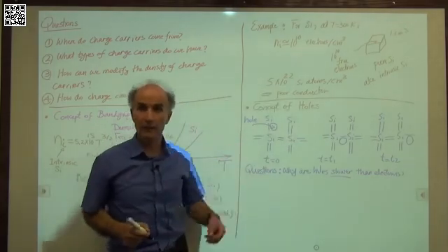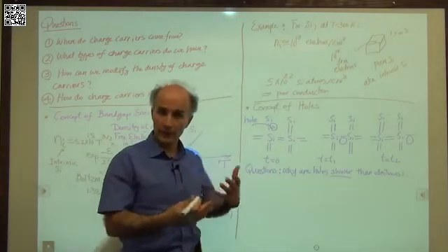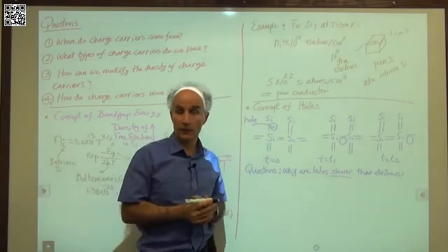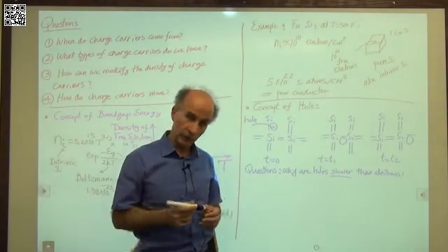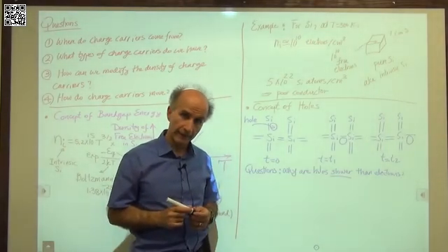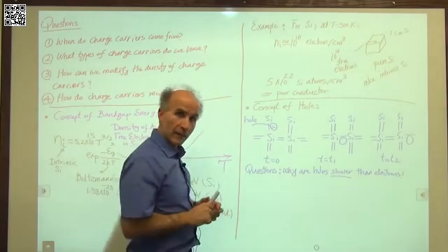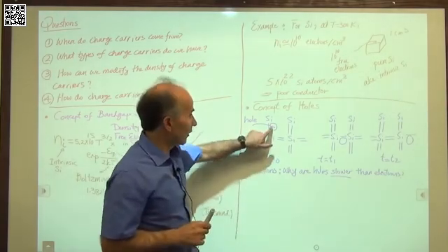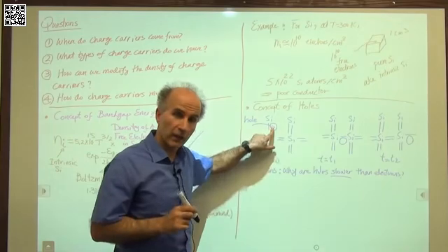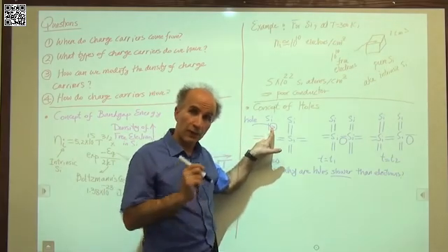Okay, as we will see later, when we give properties to electrons and holes, we say holes are slower, maybe by a factor of 2. Why is that? Well, you can see here that the way this hole moved was actually by electrons being released